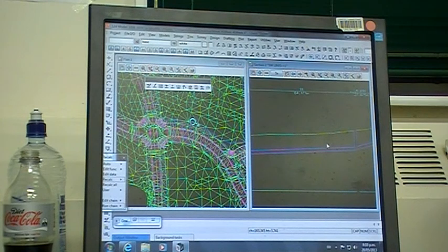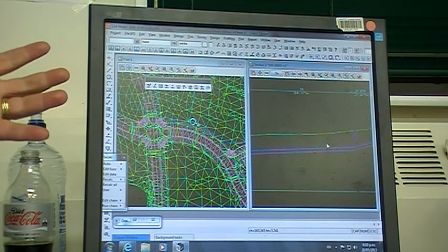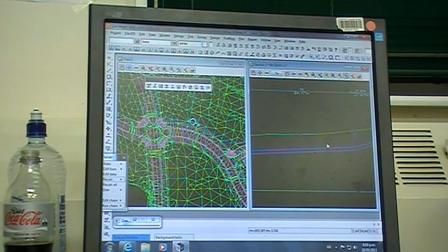If you're designing something that was going to be put in trenchlessly, would there be much difference in how you designed it? Not really. There's different things you'd have to consider. You don't have to worry about the same cover problems quite often with trenchless technology. But then the whole thing that's driven you to trenchless technology might be, I've got one at the moment where I have to go under some protected trees, so I have to get an arborist to direct how deep I go, so I don't touch root balls.